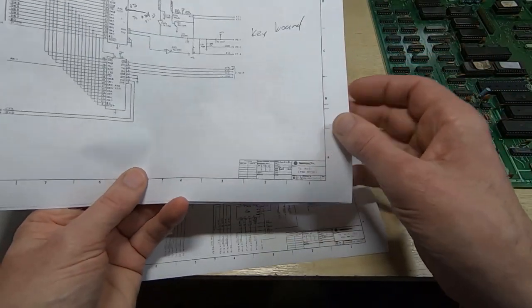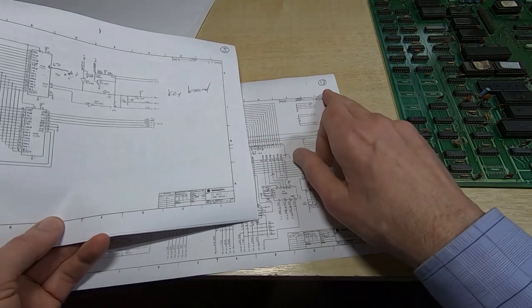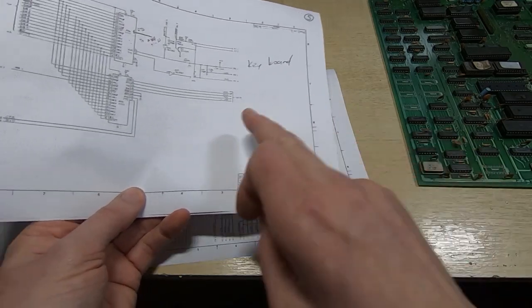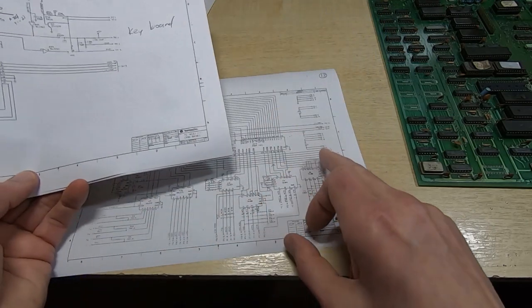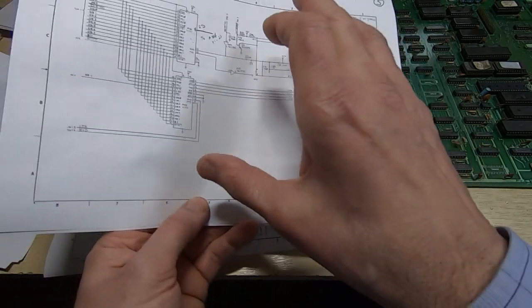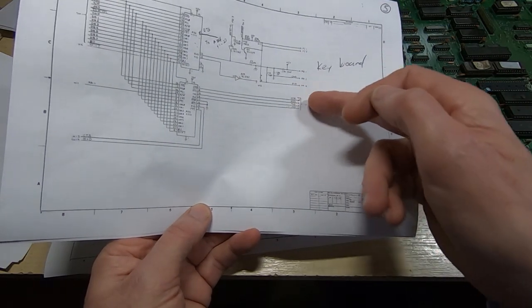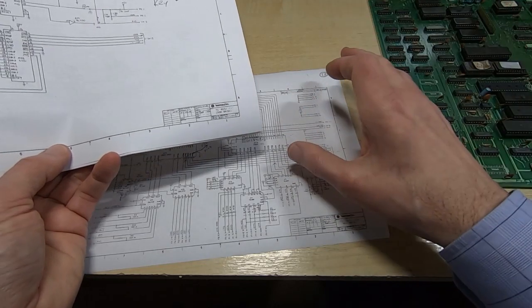we have those same lines coming in here, and this says sheet 13, which is the sheet number for these connections. So these connections go to here, and it's really just a serial connection going between the Z80 and the 6502 dumb terminal. This is the only real connection between the two. It doesn't share data buses, doesn't share address buses.